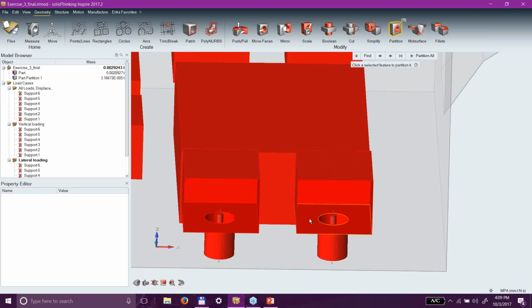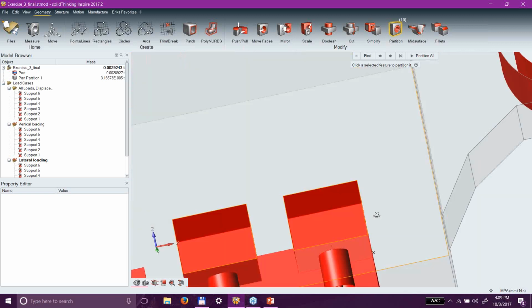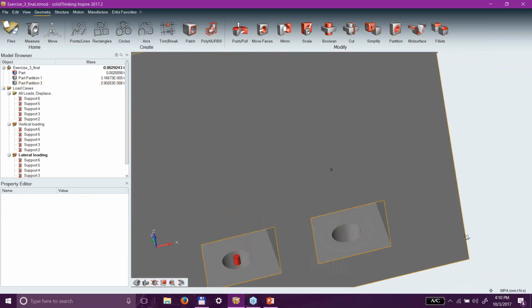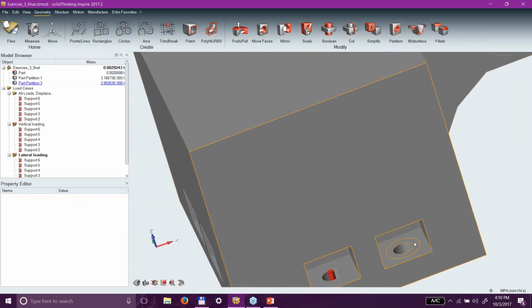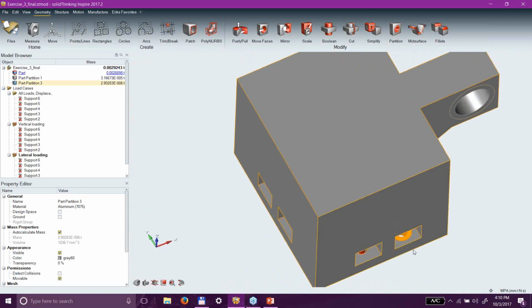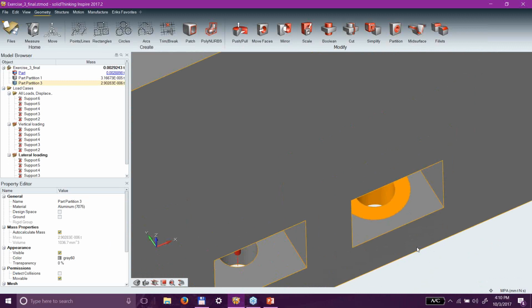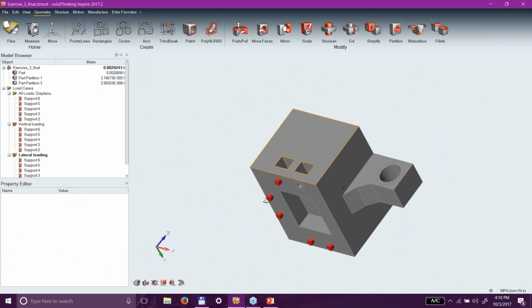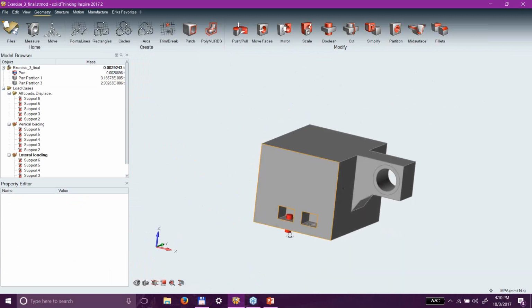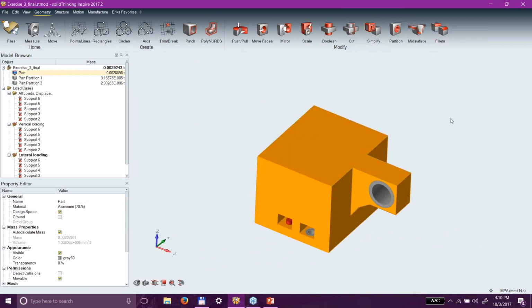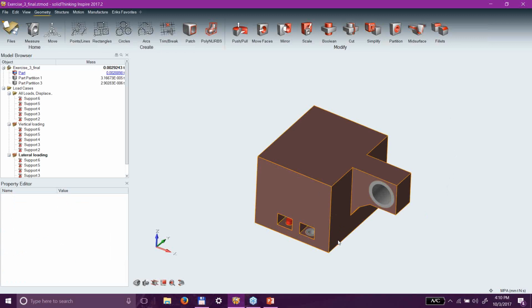protected. So what I'm going to do is actually control click. I'm going to remove that surface there. And now if I select that hole, I just get what I need, which is a cylinder around the hole. And I can now go through and do it to all 6 mounting holes on my part. And after I did that, I would have the perfect design space. And then all I would need to do is right click on it and select that as design space. And then that gets carved away when I do my optimization, which is what we'll describe next.